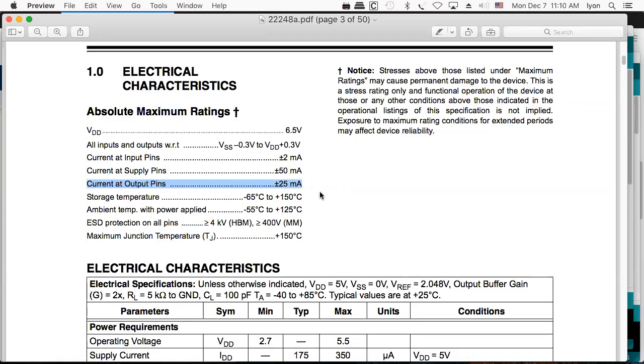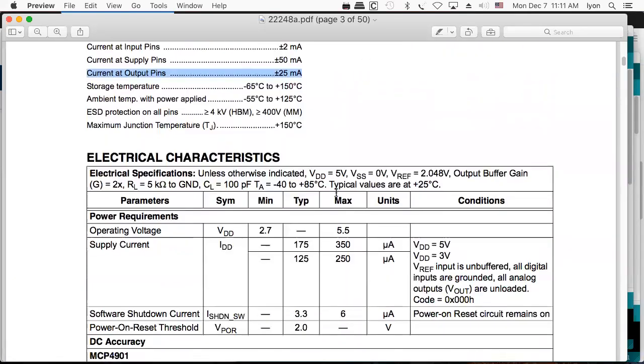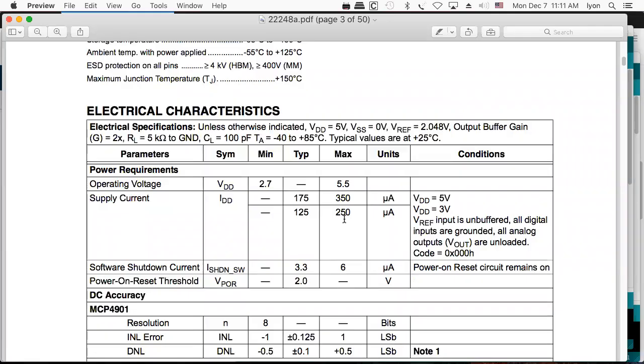And so that's why I say, look, you've got to have amplified speakers or a very low power crystal piece, phone jacks or iPod headphones or something that's not going to draw a lot of power, because this thing does not have a lot of power for you to draw upon. And you can tell that right away because of the data sheet, right? He just doesn't have it. In fact, if you look at current draw, it's measured in microamps.